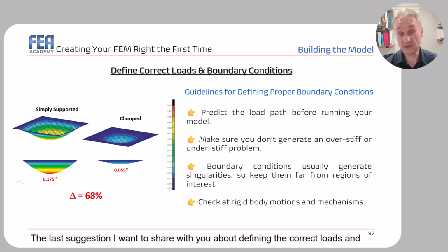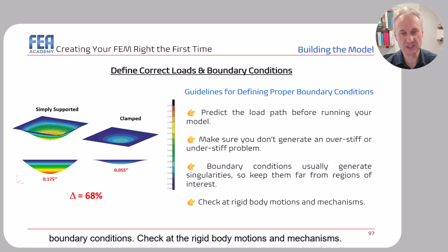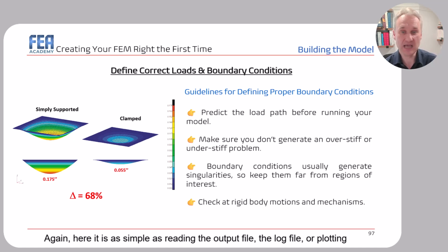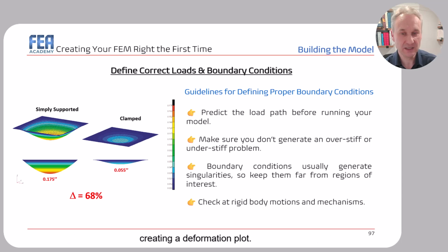Finally, the last suggestion I want to share with you about defining the correct loads and boundary conditions: check for rigid body motions and mechanisms. Again, here it is as simple as reading the output file, the log file, or creating a deformation plot.